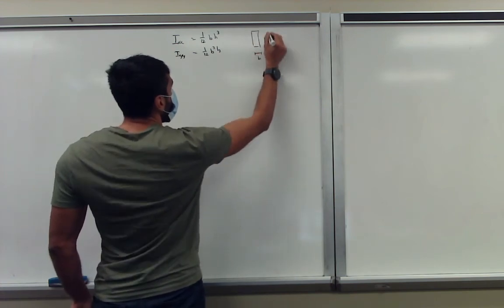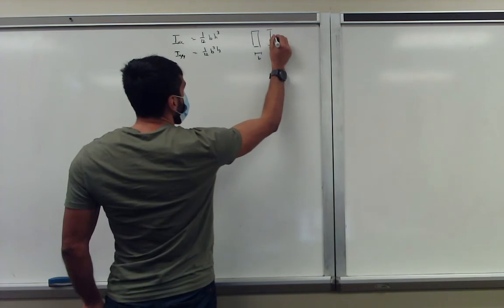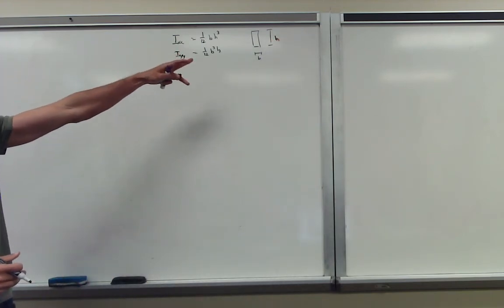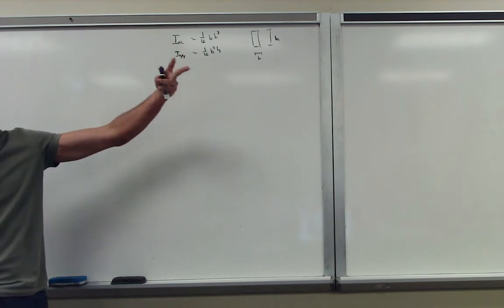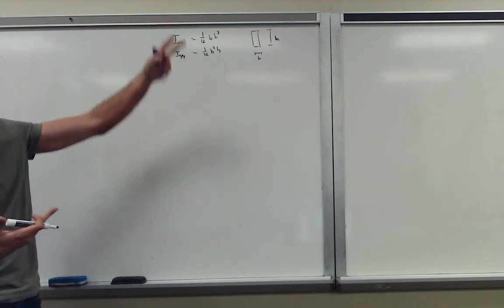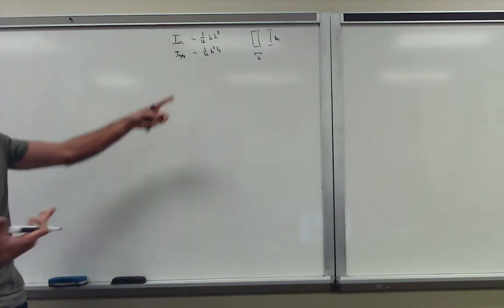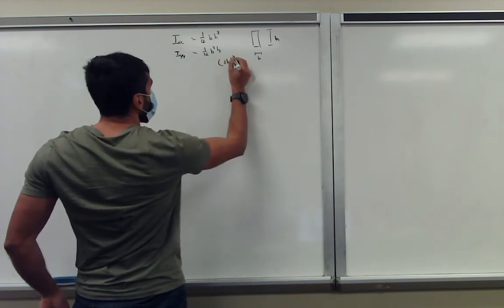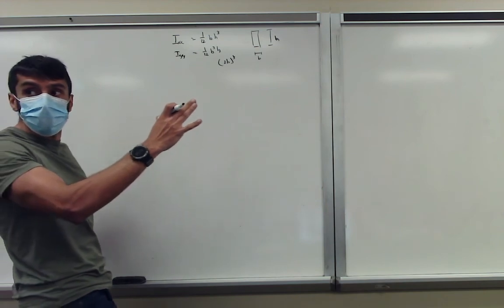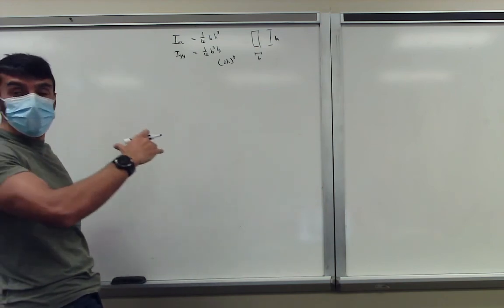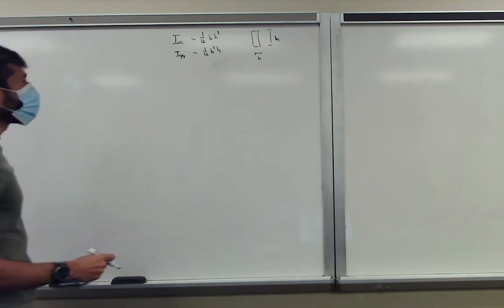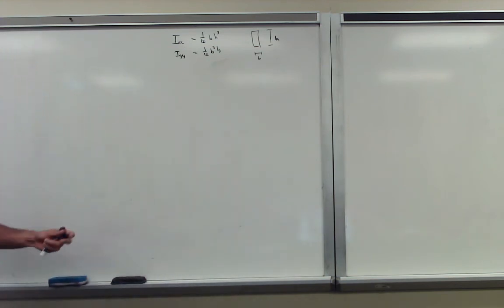B and h is our rectangle, right? And then, of course, if it's thickness, then the b becomes a t. If h is 2h, then it becomes 2h to the power of 3, etc. So just be careful when it's a 2h. You take 2h to the power of 3, not just the h part component. This is a full length to the power of 3. Okay? So these two are always easy to use, and then together with this time term, we basically can solve